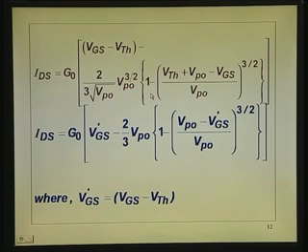Inside this, now you see the whole equation becomes smaller: 1 minus Vgs dash, which is Vgs minus V threshold, and Vp0 retained. I have not made any changes. All that I have done is put Vgs dash equal to Vgs minus V threshold. So, now you get this quantity here. How do we simplify this? It is a slightly unpleasant equation to look at, but we will see it further.